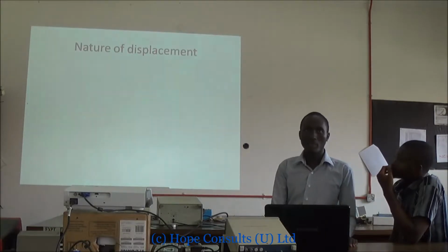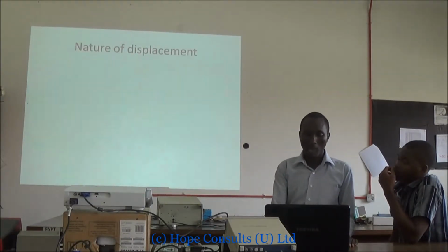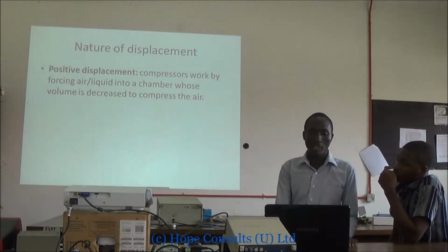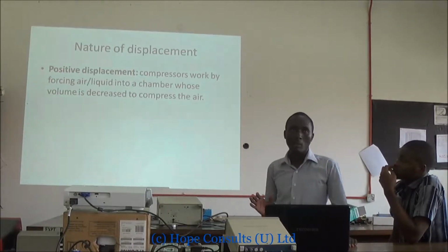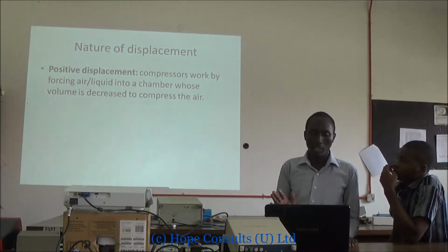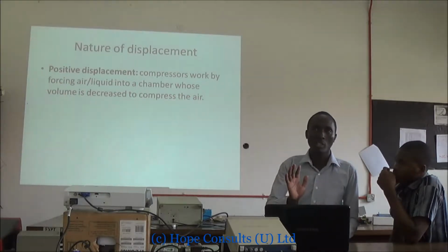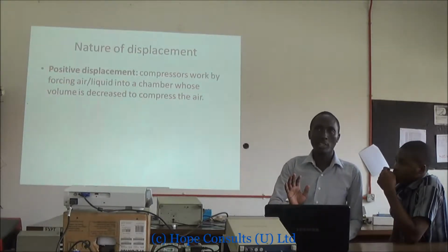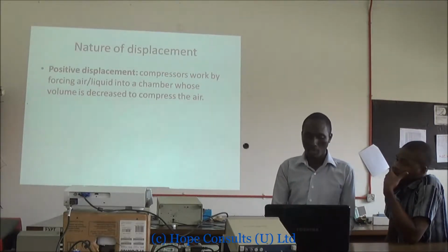The nature of displacement of the compressor, we have two natures. One is the positive displacement. Here we are mainly forcing the air or the liquid into the chamber. So we reduce volume. We are using a shaft or a piston. You push to reduce volume, and by doing that you are increasing pressure.